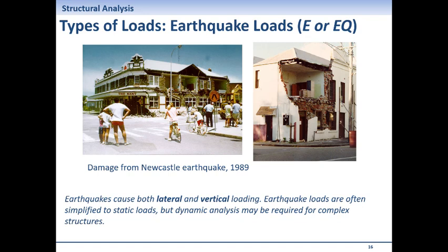But it's mainly dead versus live, because dead we know, because we can sort of deterministically say this is where the dead load is, whereas live load we never know. If I threw a party here and I had a big table of food here, nobody would go to the last row of the seats. Everybody would be, it's the same number of students, but everybody will be here. That's the problem with live load. You don't know where exactly it is. And that's an important aspect of it. So try to look at it from that perspective.